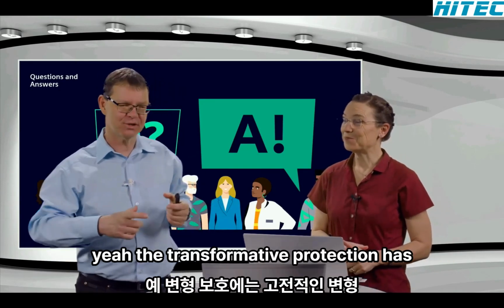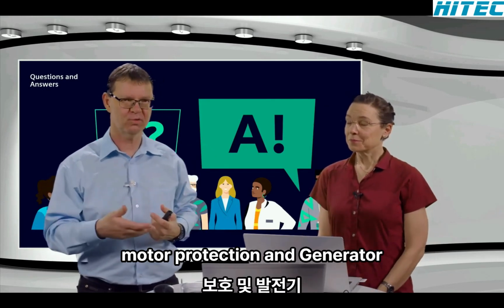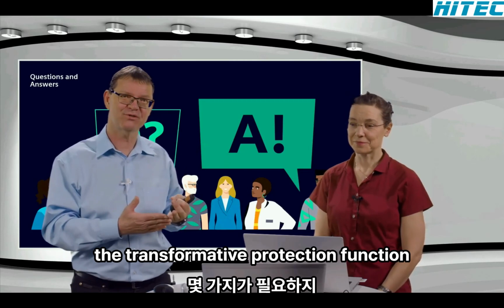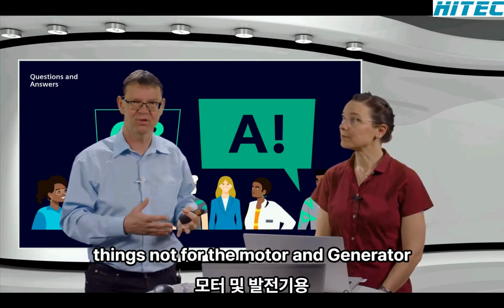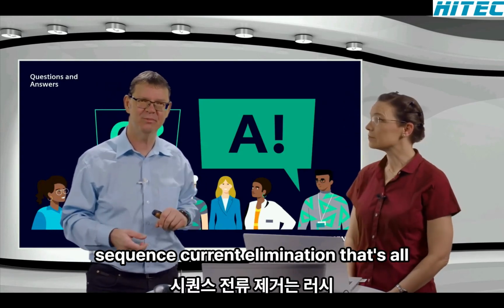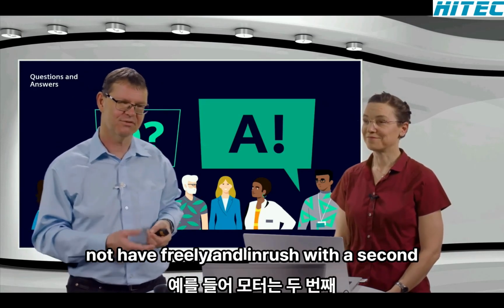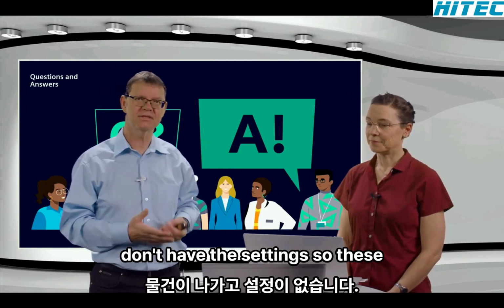The transformer protection has the classical transformer protection, and there are also the options to load motor protection and generator protection inside. As I already mentioned, it is more or less the same function as the transformer protection function, but simplified because we need a couple of things not for the motor and generator. For example, vector group shift, zero sequence current elimination, that's all stuff only we encounter for the transformer protection. Inrush protection, for example, motor does not have really an inrush with the second harmonic. So that stuff is out and you don't have the settings.